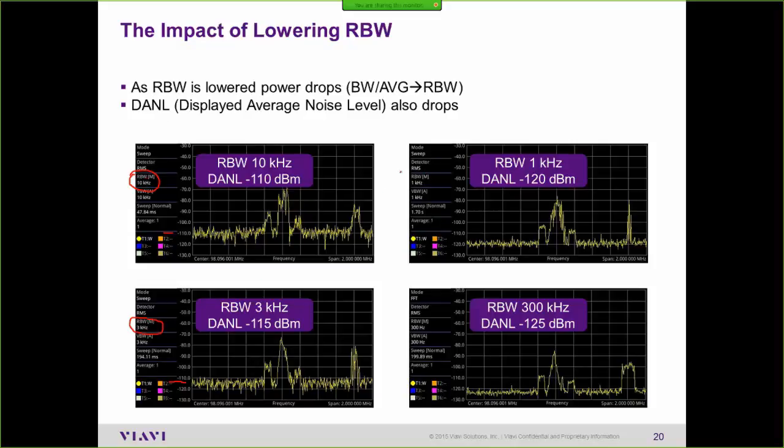The peaks on those transmitters are dropping too because I'm taking smaller slices of them. So lowering the RBW gives you more slices across the screen, and it shifts the whole line downward because the amount of power being measured in each little bin is less.